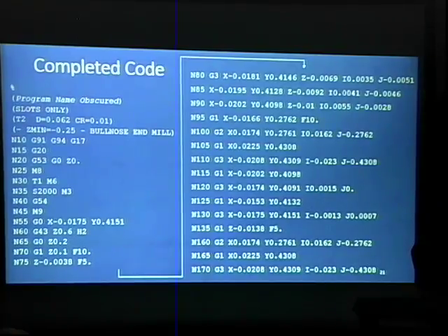Okay, that moves the tool down 3.8 thousandths of an inch. Line 80 then moves it 18 thousandths of an inch in the X, 0.4 inches in the Y, and down 7 thousandths of an inch. You can see why we don't want to write these things by hand, because from N80 down through N170 is the same basic concept, right? We see G1, G2, G1, G3, over and over and over again with just different numbers in there. And because we can't store variables, because we have to feed it numbers, writing this by hand is troublesome.